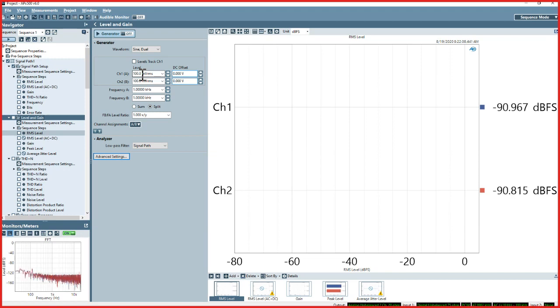The downside to the PDM module is that SACD uses one data line per channel, and the PDM module has only one data line, so you would only be able to test the left or right channel at a time. But that would be another possibility, and there are many steps in between, because there are some things that support SACD over I²S and some other things. So that might be an answer where we need to get some more detail about the physical device under test to usefully answer that question.